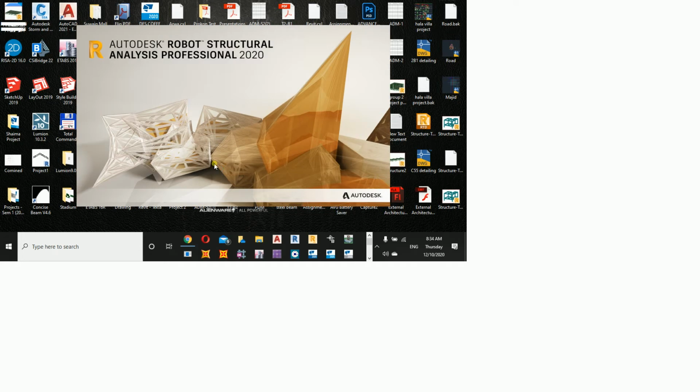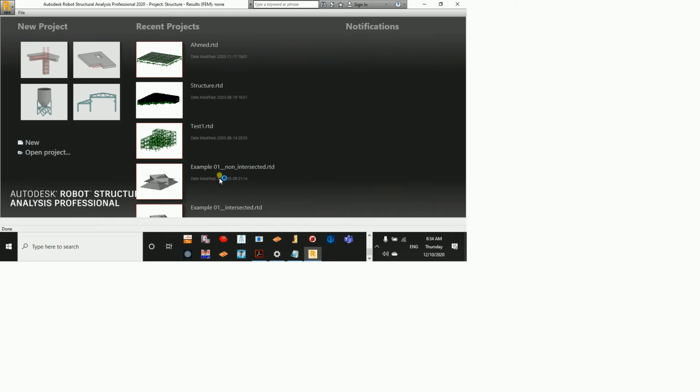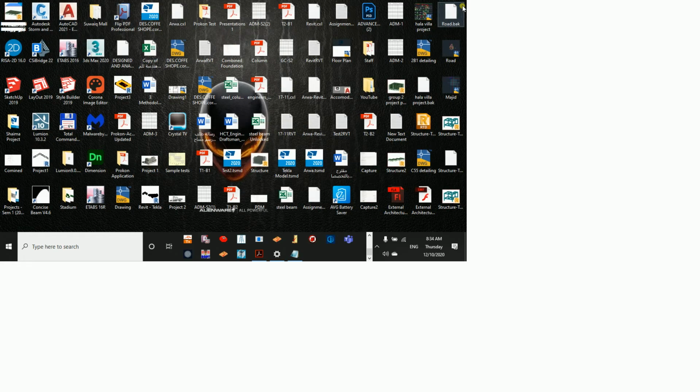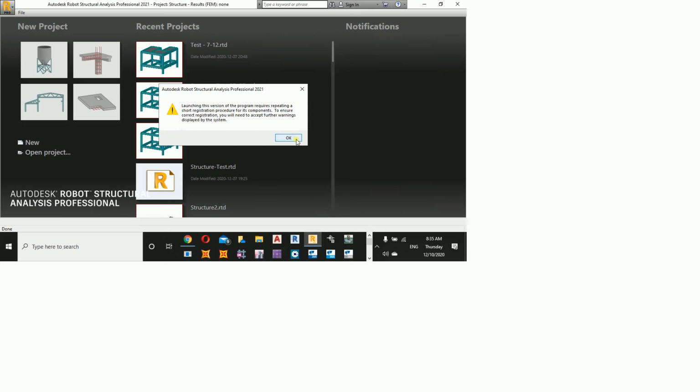Now, if you are having a higher version, what shall you do? You cannot lower it. That's the biggest issue. Okay, I'll show you. I think you are having all of you 2020, right? All of you are 2020. So what I'm going to do now, the only way to do it, is to export it as IFC.